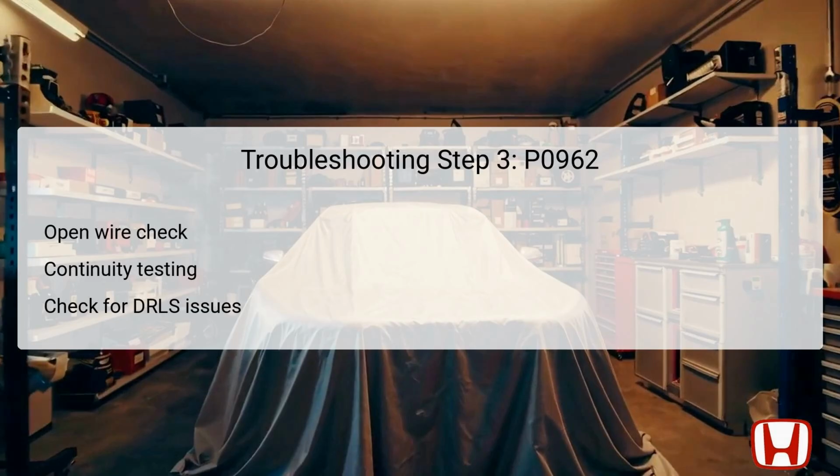Initially, ensure the vehicle is turned off and in a locked position. Next, use the HDS to jump the SCS line, preparing the vehicle for diagnostic checks. Disconnect both the PCM connector C and the solenoid wire harness to prevent interference during testing. With both connectors disconnected, continuity must be checked between designated test points. Specifically, continuity should be verified between the solenoid wire harness and the PCM terminal points.